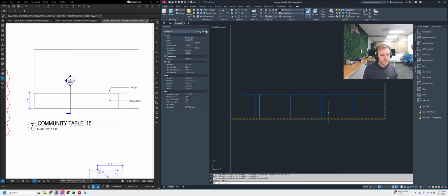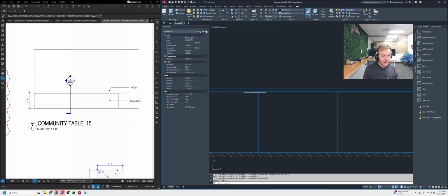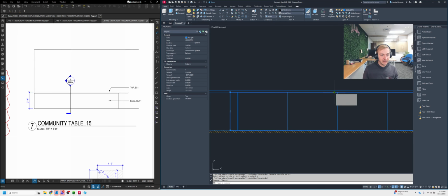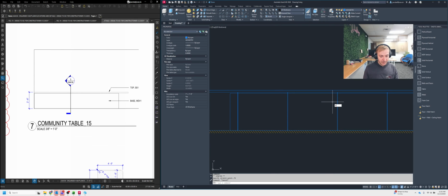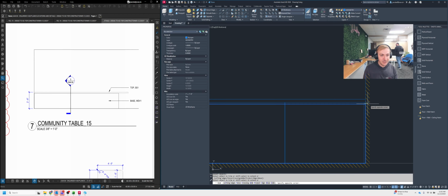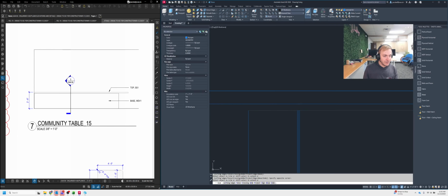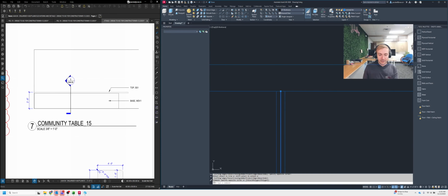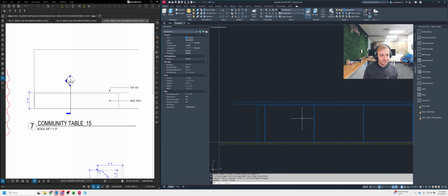And then we want to throw in our 3/4 inch reveal at the top here too for the liftoff space. So we're going to bring this box down 0.75. And we're going to trim these lines one more time. Sorry about that. I should have caught that earlier. Trim these lines back to here. Okay. That line's extra. It doesn't need to be there. Okay. So you can see that reveal there.